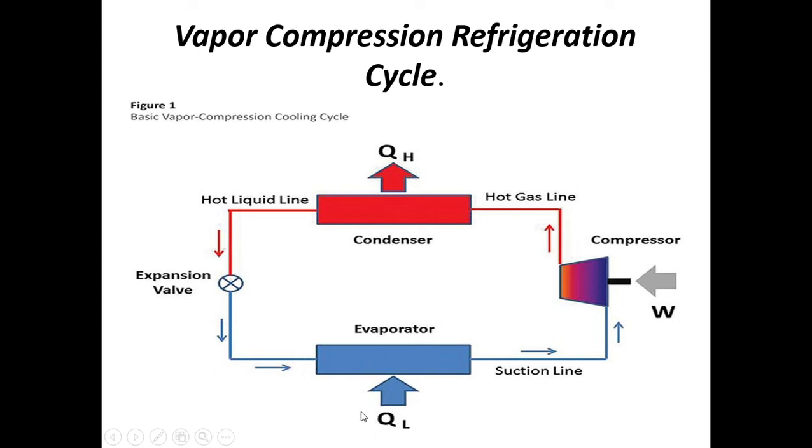So what happens is, heat will flow from the space to be cooled to the refrigerant, which is at a lower temperature. From here heat enters the refrigerant. This heat will be the latent heat of the refrigerant, so the refrigerant absorbs its latent heat during its passage through the evaporator coil and gets vaporized. Next, after the evaporator, vapor refrigerant comes out. That refrigerant is sucked by the compressor, which increases the pressure and sends the higher pressure refrigerant into the condenser for the next cycle.